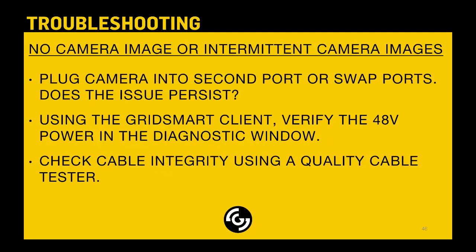And then you want to check the cable integrity, again, using a good quality cable tester. A lot of times you'll find out real quick that the cable that was thought to be 280 feet is actually 320. And a lot of times you can find 20 feet in a pull box and another 20 feet in a mounting structure, and just be able to cut out the excess, and then you're good to go.